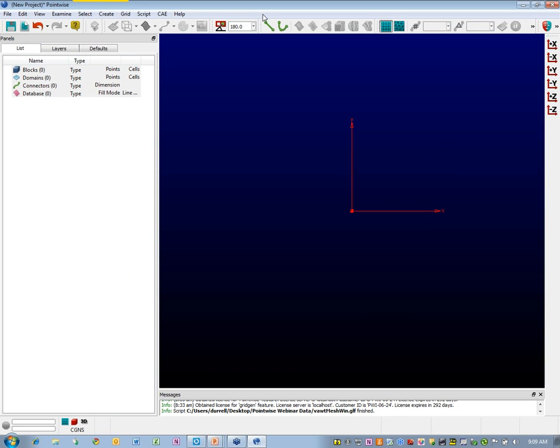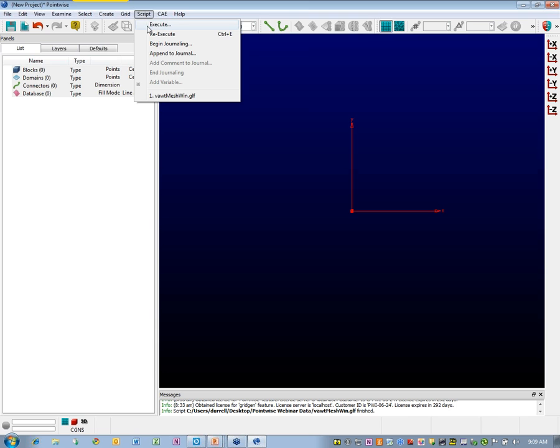Okay, well, for Travis's work, Pointwise was used for both geometry creation and mesh generation. It was Pointwise's scripting language that we call Glyph that tied all this together. And Glyph is built on top of Tcl. It's an open, well-documented, very mature dynamic programming language. And Glyph is essentially just a suite of Tcl functions that give the user access to all of Pointwise's capabilities. Also included with Tcl is the GUI toolkit called Tk. And this essentially allows you to write your own customized GUI interfaces. So I'm just going to show you all this in action.